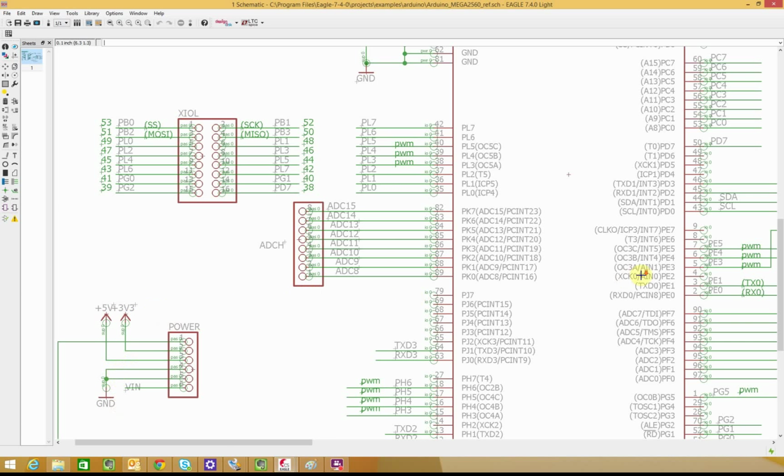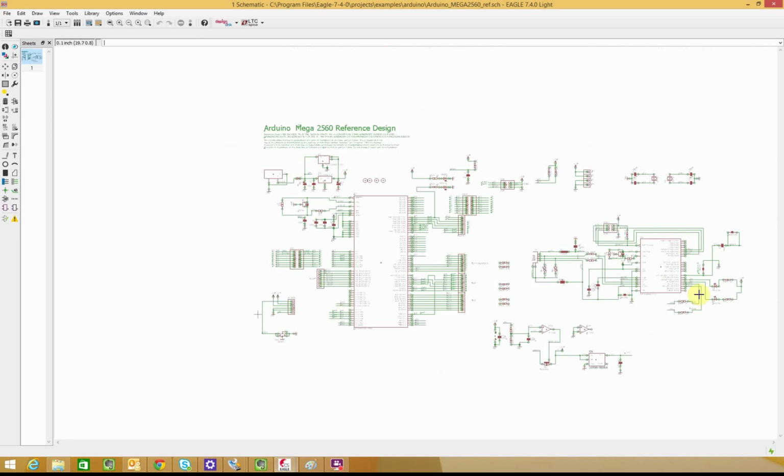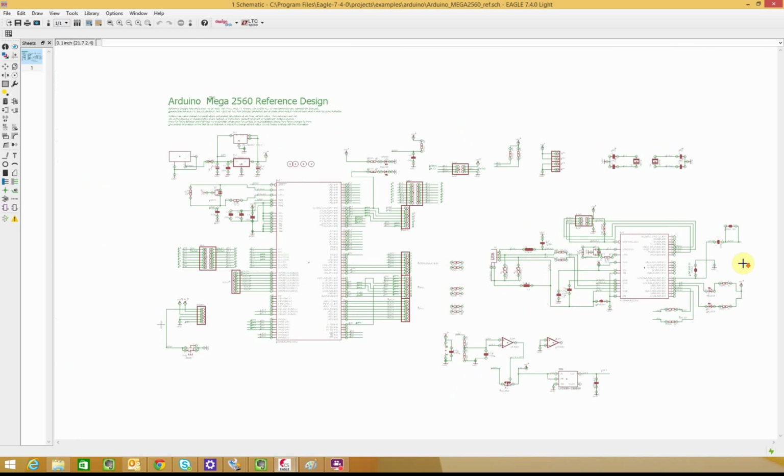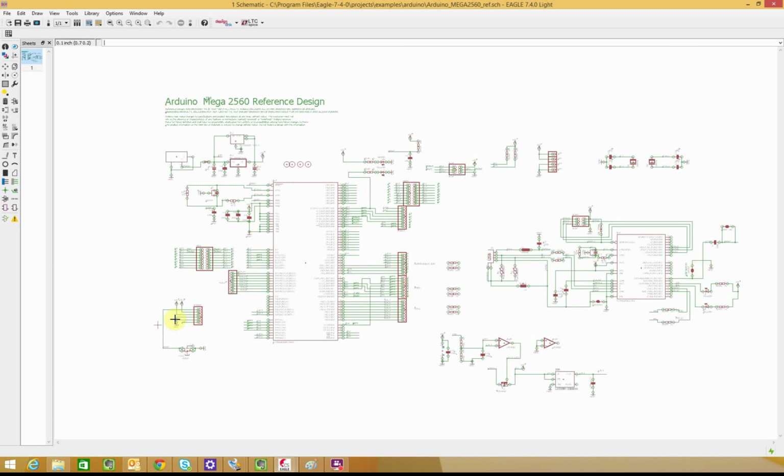And they're using this to maintain a clear diagram that's easy to read, because they don't have to draw all the power pins around in the circuit. They can just have these references, and then the software will handle the connection and make sure that all these pins and nets with these names are routed together when you go to the PCB layout system. So it really makes the diagram much easier to read, because you don't have to follow all the lines of power net. So that's the reason for it.